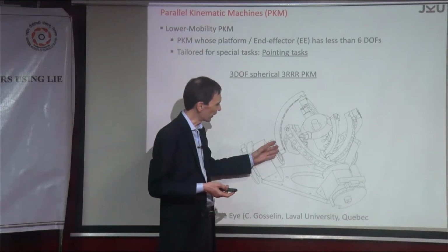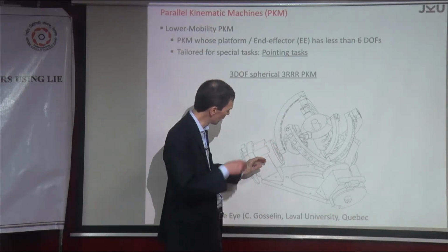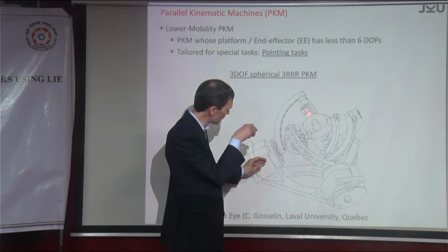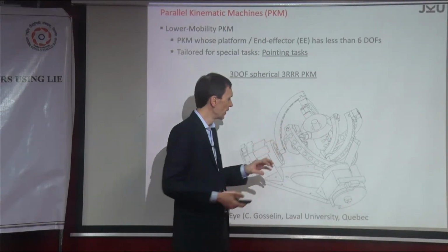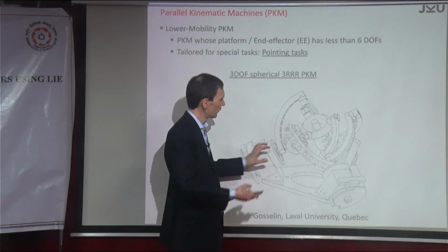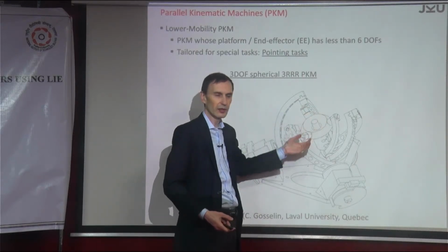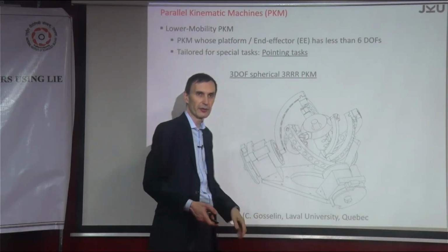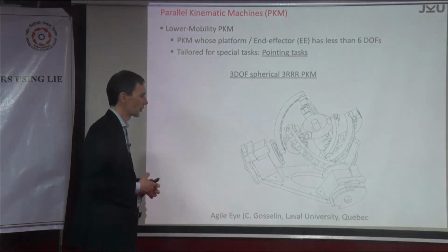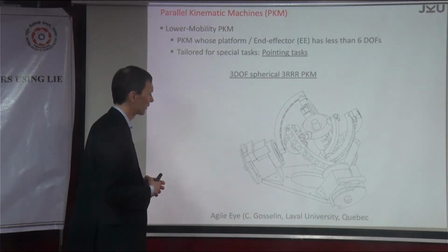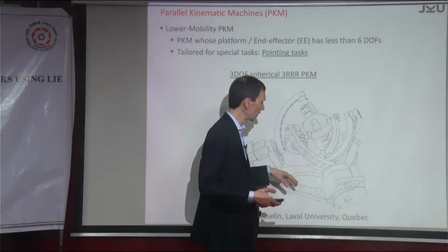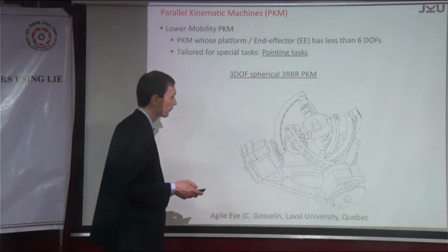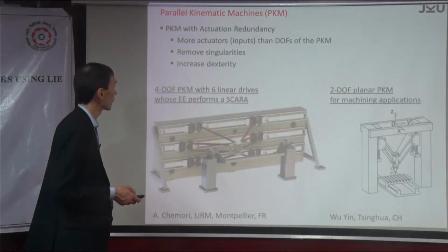And they are turning. Again, this is a spherical mechanism, because if you look at what happens here, we have 1 revolute joint, and the other one comes here. So they all intersect again in 1 point. Okay. So whatever they do, they can only turn this, let's call it, platform. If you have a pointing device, then this is easily positioned, and also it's very agile, because the moving mass is very low, and you can have very high and precise motions.